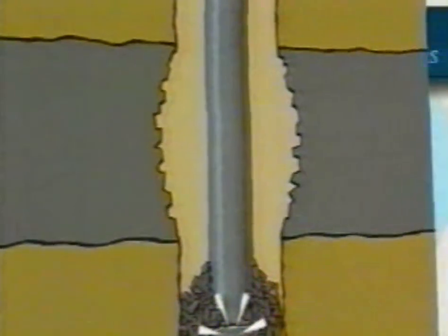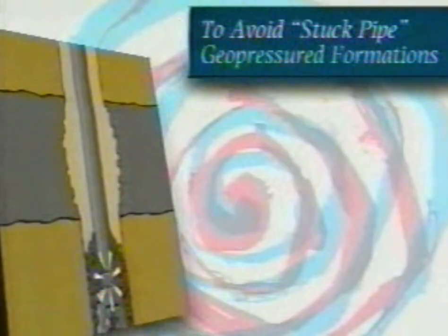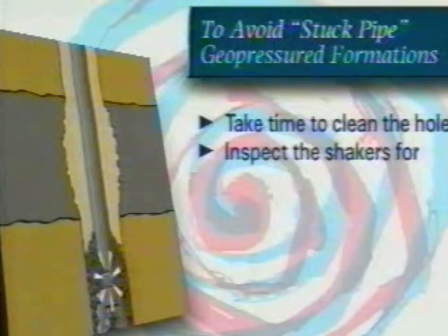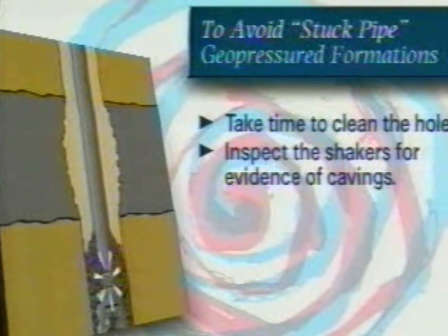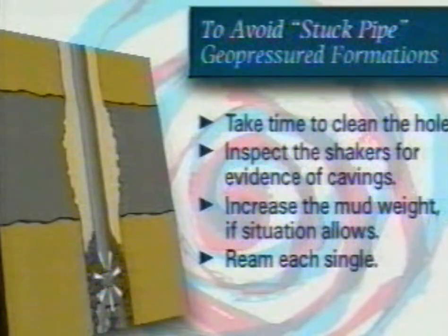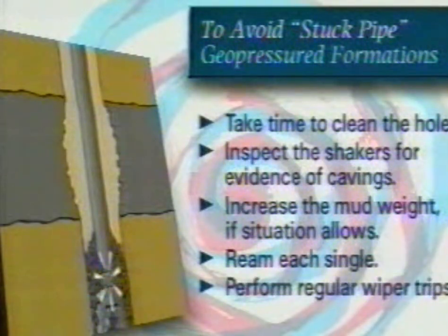To avoid stuck pipe in geopressured formations, the following action should be taken into consideration. Take time to clean the hole. Inspect the shakers for evidence of cavings. Increase the mud weight if the situation allows. Ream each single. Perform regular wiper trips.